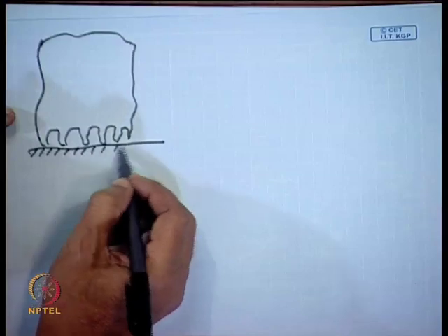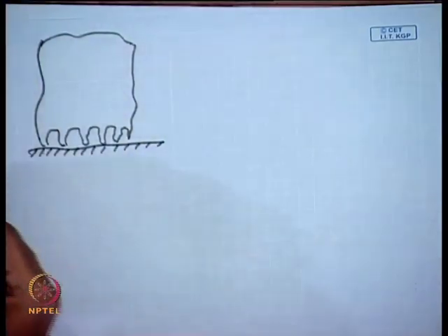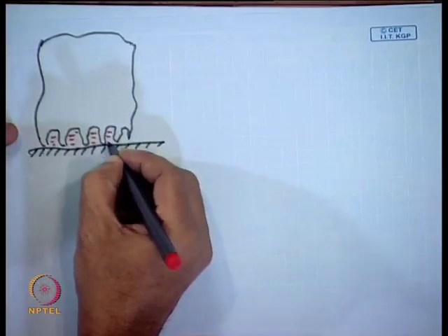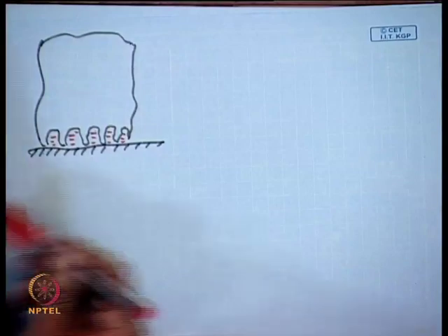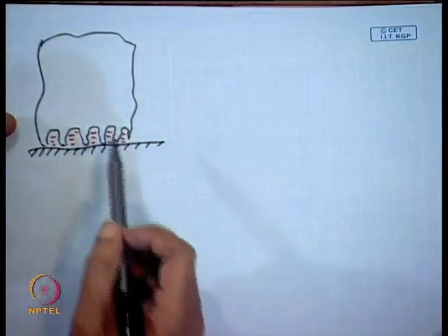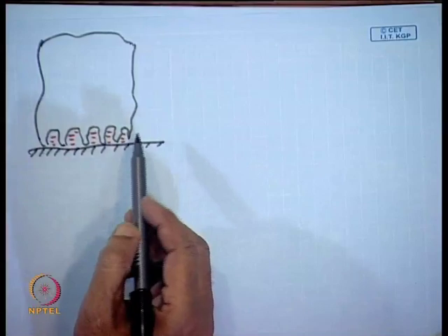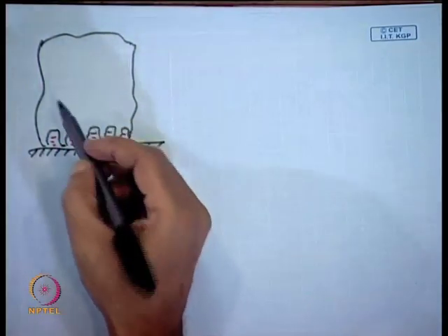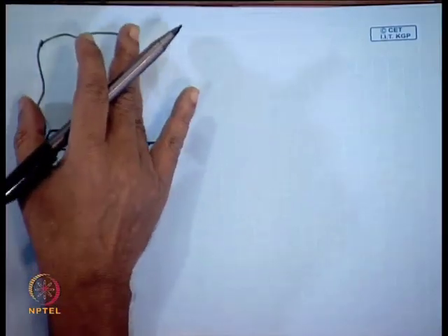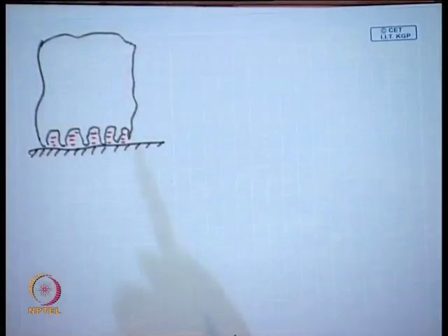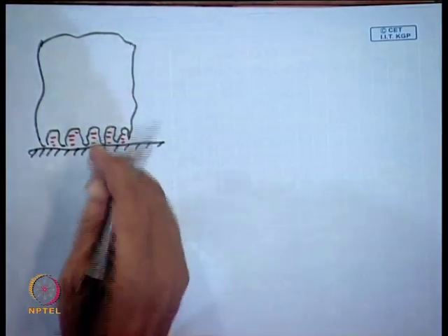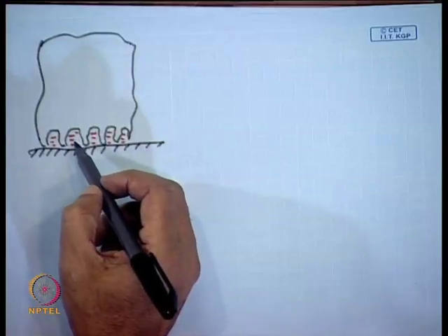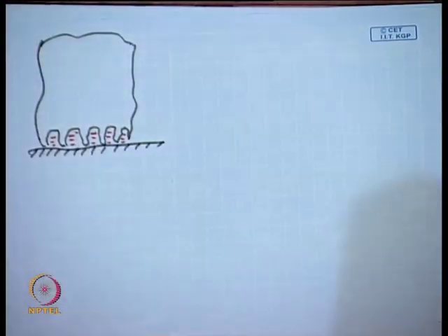This is sustained by the evaporation which is coming from here, because that is the place where it has a connection with the liquid. Now, this vapor jet cannot grow infinitely, somewhere this vapor slug will break and leave the surface. Till it leaves the surface, it is getting the supply of vapor from this liquid.